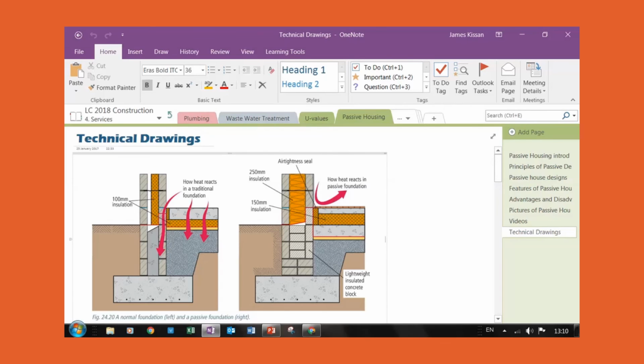So when we're building this, before this house is plastered, we come along with tape and we tape any joints. A joint would be where the wall meets the floor. That's a joint, so we come along with tape and we tape that joint. And the reason we tape that joint is so that no air will go between the floor and the wall.